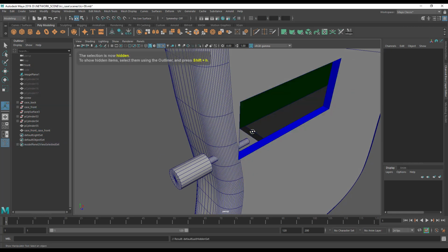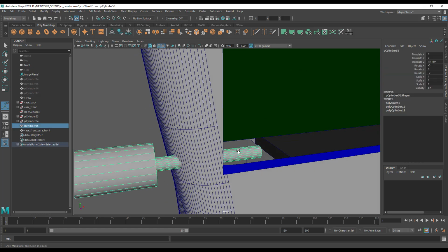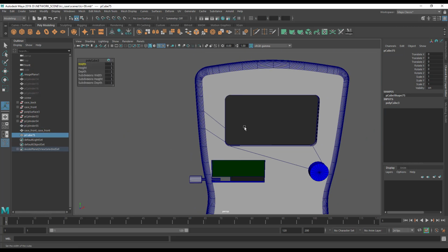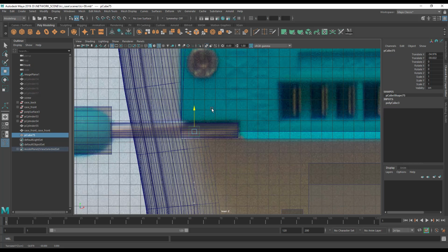Now I'm going to hide this zip socket representation, and I need something this thickness to cut the bar. So I'm going to do this one by eye. I'm going to bring in a box. I am going to line it up, so this is not the best view for it. I'm going to make it this thick, just ever so slightly thicker actually. I don't want to be chopping huge holes in here. But I do want to give myself enough clearance to make sure I am good.